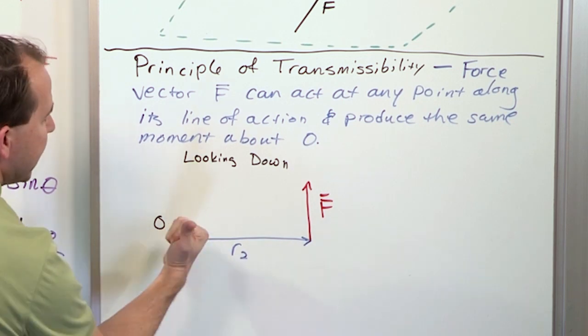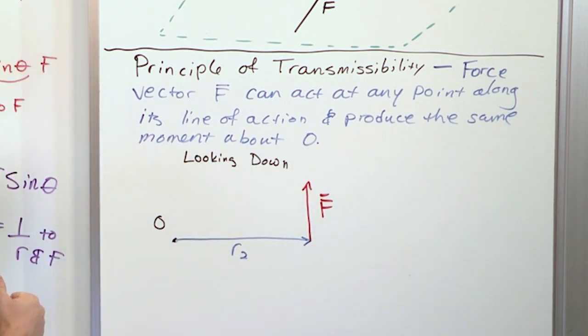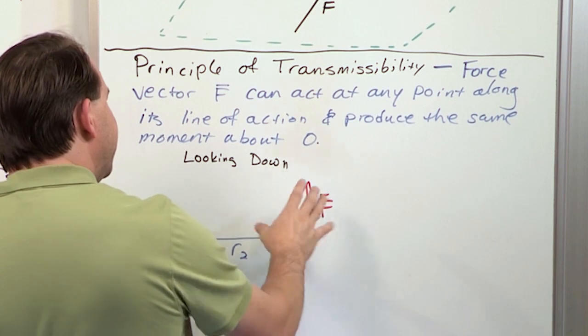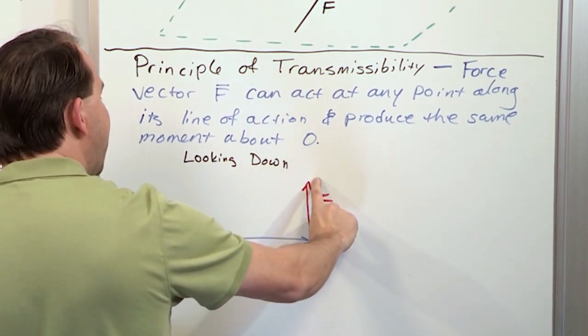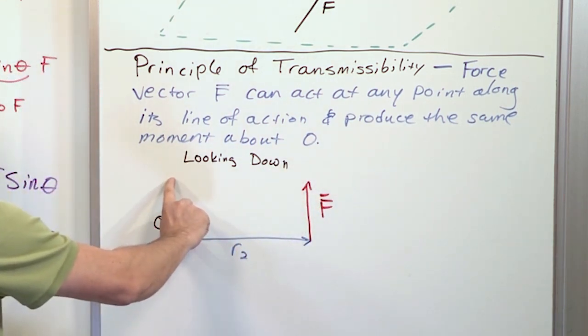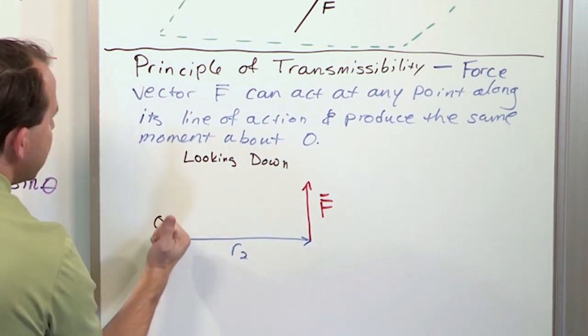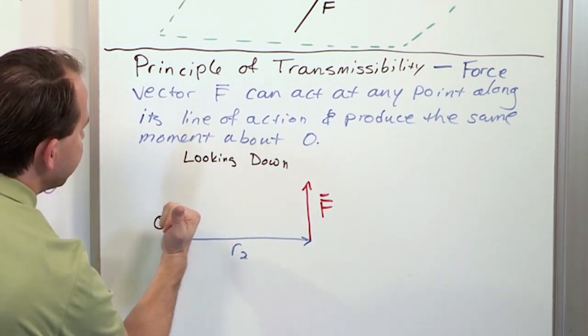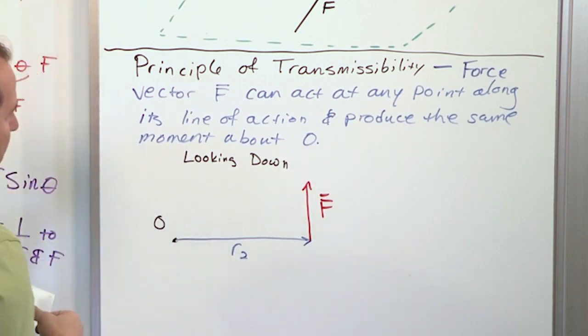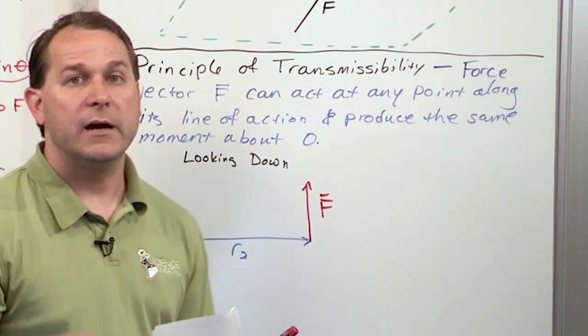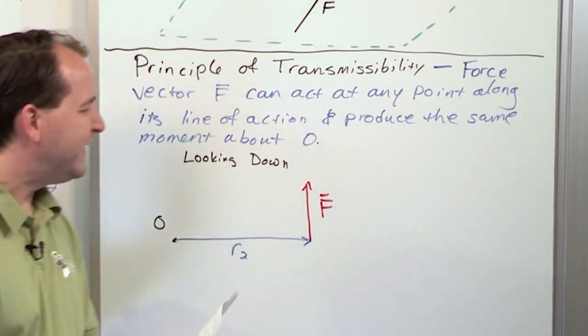So it's going to rotate it, and the moment vector is going to actually point out of the board. Now, that's the way we did it two-dimensionally, but if you move F tail to tail with this vector here and do R cross F, you get exactly the same thing. R cross F is providing a moment vector out of the board, just as we talked about a minute ago before. Now, this particular one's real easy.